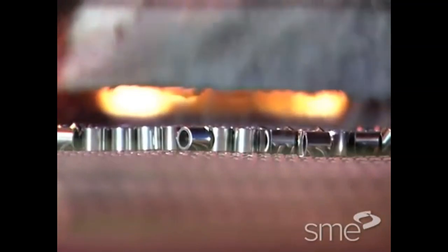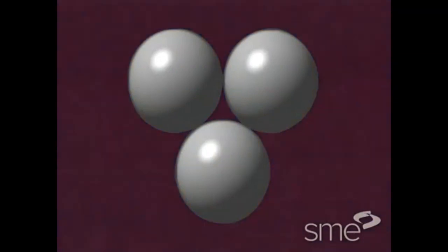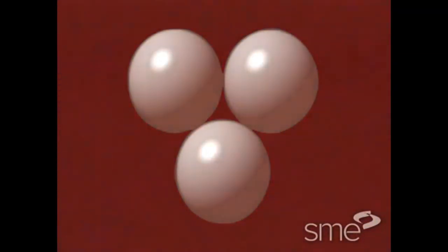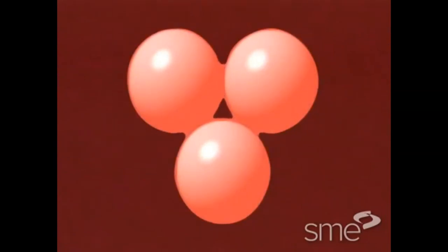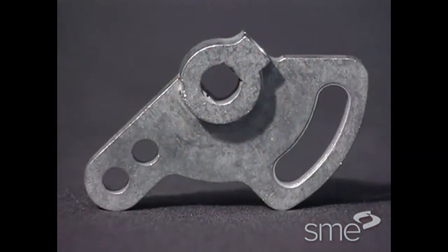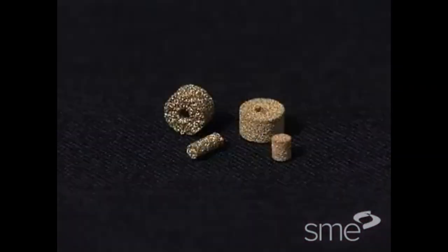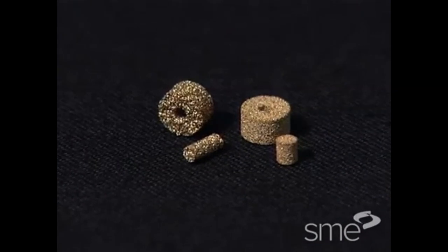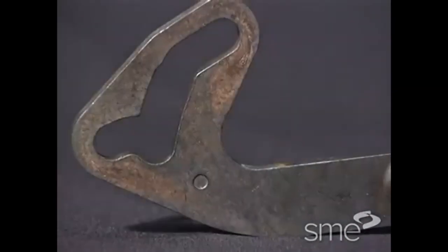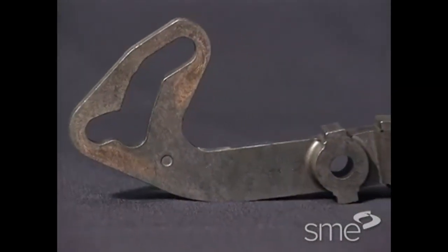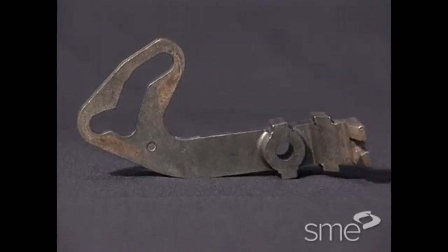The parts are then transferred to a sintering furnace. During sintering, parts are heated at a temperature below the melting point or range of the base metal, but high enough to metallurgically bond the individual particles. Sintering further densifies the parts, increasing strength. Final part density is extremely important. Although controlled porosity is required and achievable for certain parts, the performance of structural parts increases directly with increasing density.